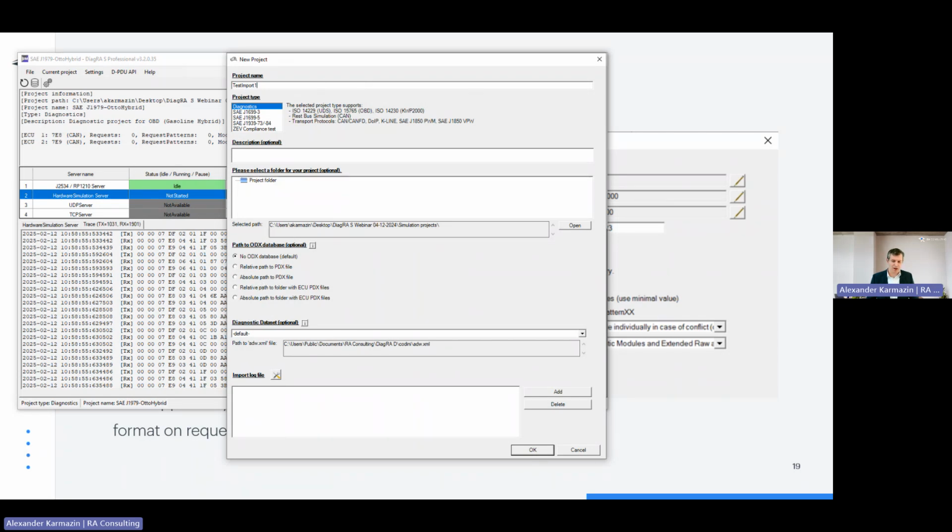For example, if you have a trace file, then the tool needs to know which CAN identifiers are identifiers for diagnostics for ECUs, and which CAN identifiers are just functional request IDs or just rest bus CAN IDs with CAN signals which have no diagnostic data. And such a configuration is easier if you have a configuration for it as an ODX database.